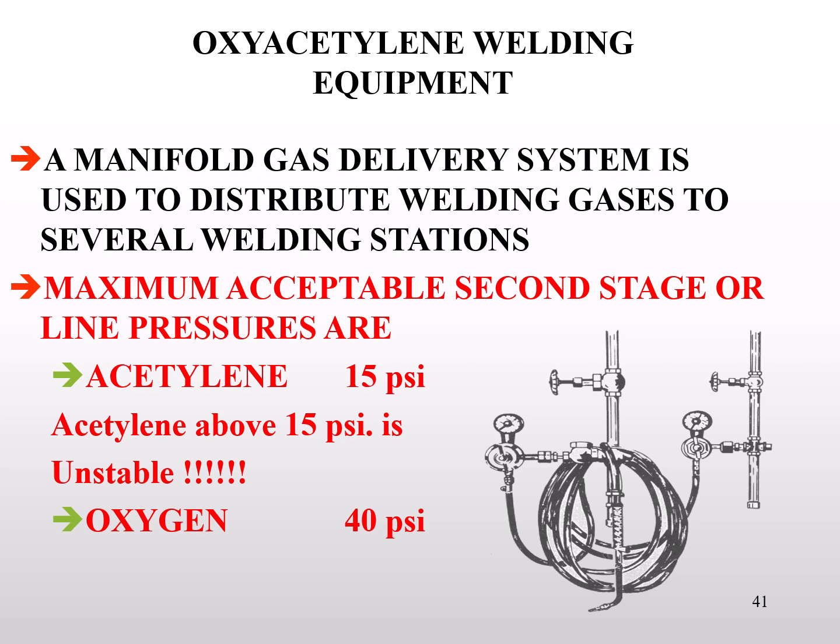There are some maximums for our working gas pressures. Acetylene, we try to limit to no higher than 15 psi. Above 15 psi, acetylene becomes unstable. Oxygen's generally limited to 40 psi. As per the norm, we would always go back and look at our manufacturer's information for our torch equipment, and we would set up accordingly. Typically, as you change tip sizes on welding torches, you would need to adjust your pressure to accommodate each tip size.